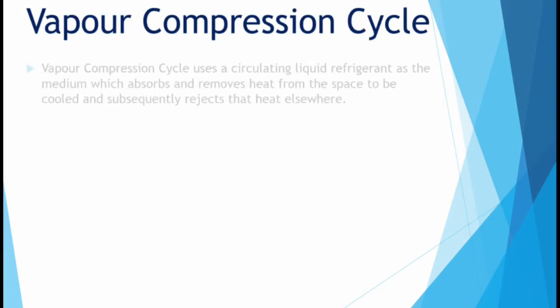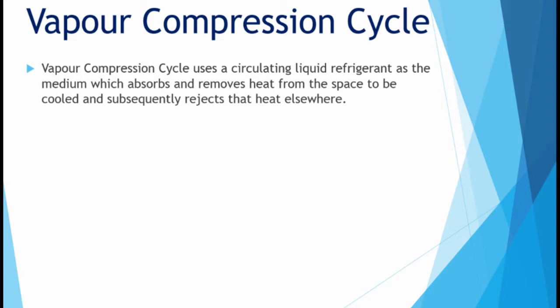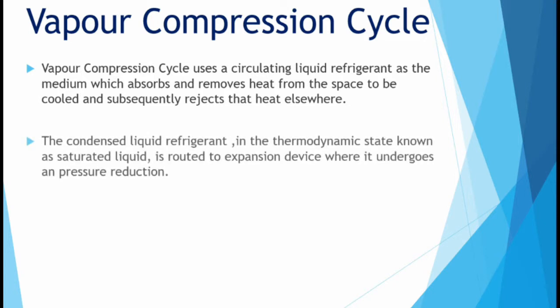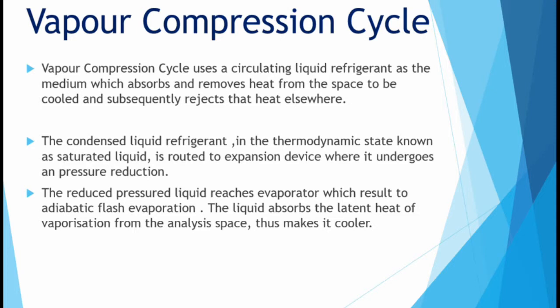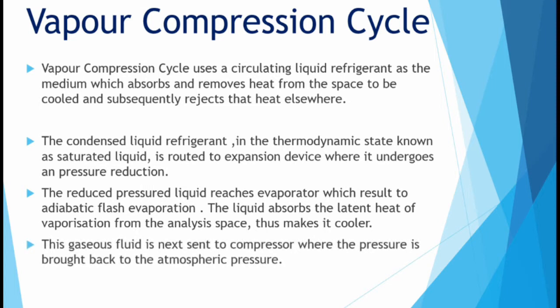Vapor compression refrigeration, VCR, is a system in which the refrigerant undergoes phase change. It is one of the many refrigeration cycles and the most widely used method for air conditioning of buildings. A standard VCR system has four components: a compressor, a condenser, an expansion valve, or a throttling valve, and an evaporator. The work is input through the compressor.